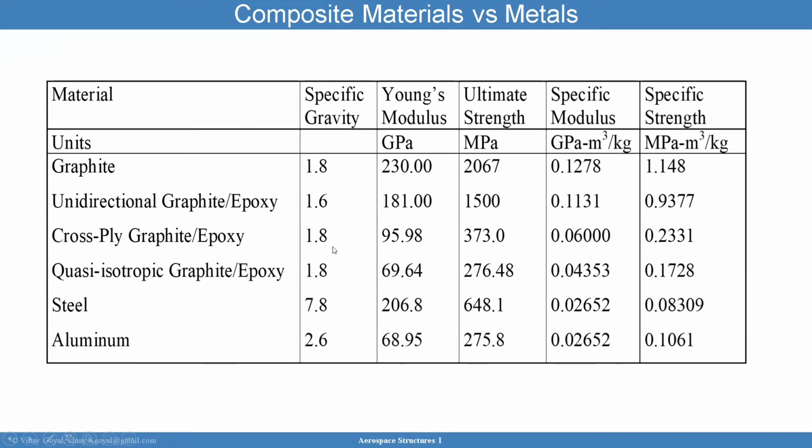That's why it's so important to tailor composites and not just default to standard ply angles, which don't tailor anything. The whole point of composites is to stack the ply angles in such a way that you get the best strength and modulus with the lowest weight you can. Quasi-isotropic is not always the right answer, and here I'm not getting a lot of benefit. Yes, there's a weight reduction for the same strength, but it's not a humongous change.